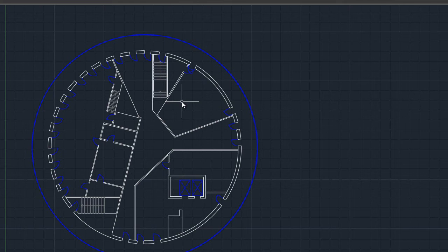Blocks are also useful if you have multiples of one object. So for example, doors. Once one block is created and copied, if you need to change it, all you have to do is make changes to that original block object, and all of them just contain that information. So I don't have to figure out where the original one is, but I can just select one of the blocks, and if I update that, it'll update throughout all the blocks.